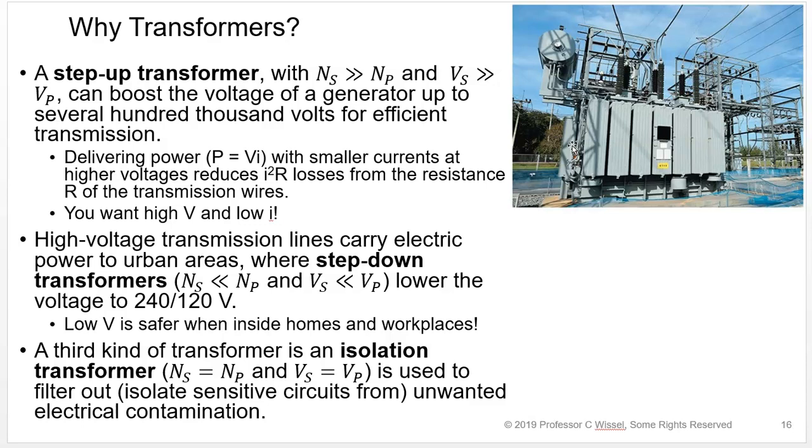It's dangerous as hell. So what they do then is they run it to another substation, and they have step-down transformers there. And they take that 36,000 volts, and they maybe drop it down to 14.5 kilovolts. My street has 14.5 kilovolts on it. And then they run it to all the different houses on the street. So it's a little sub-circuit. Okay, and there'll be a couple breakers in that circuit, and every house takes off that circuit.